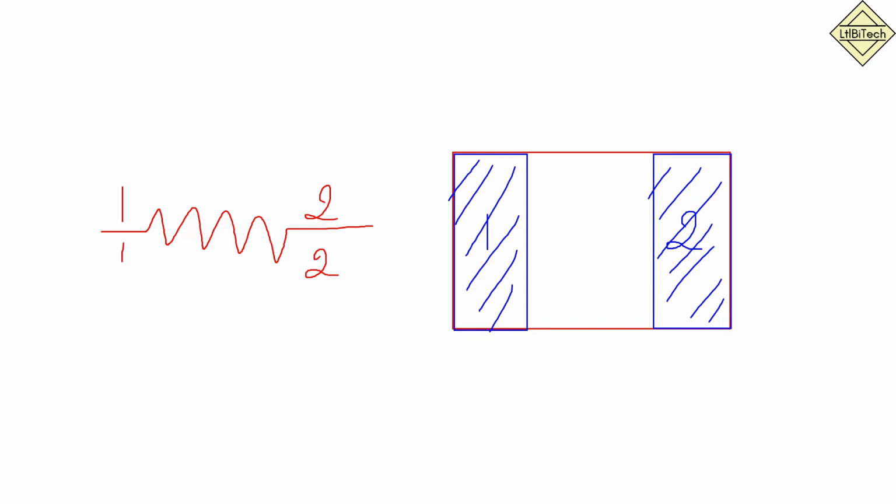This is actually where your component will be connecting all the connections according to the schematic. So in the symbol, for example, if this is R1, pin 1, the footprint pad should also have pin 1, and both should match. Similarly, if this is pin 2, there should be a pad 2.